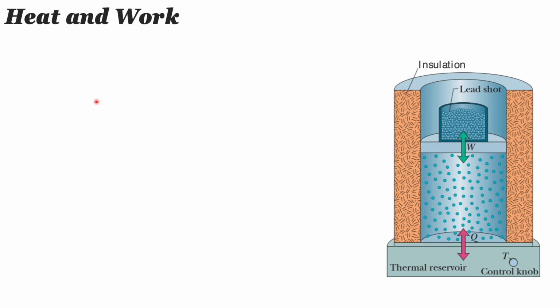Now let us find out how we can calculate the work done during each thermodynamic process. Let us consider the piston is moved up by a small displacement ds, during which the force exerted by the system remains constant, because you know that the formula for work done applies to constant force only. So if the force is variable, we have to find out the work done for the small patches during which the force remains constant and then take an overall sum.